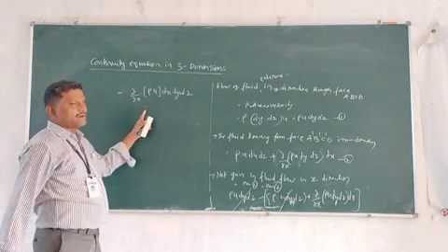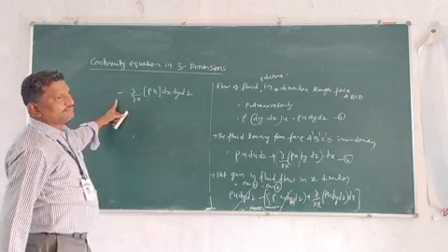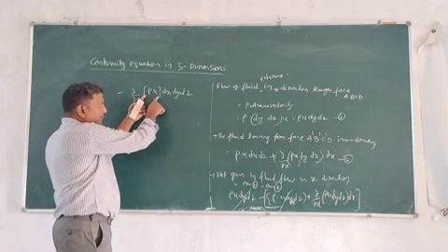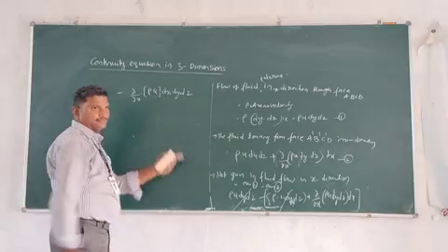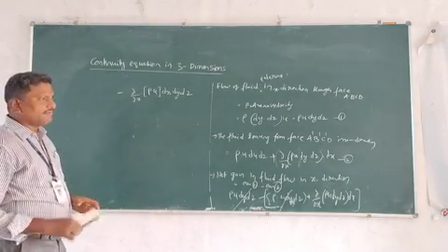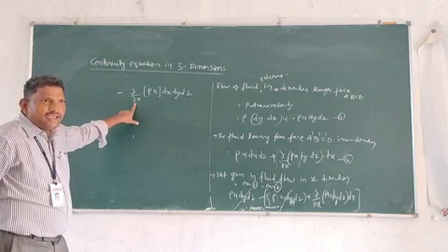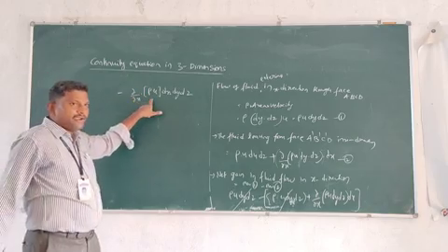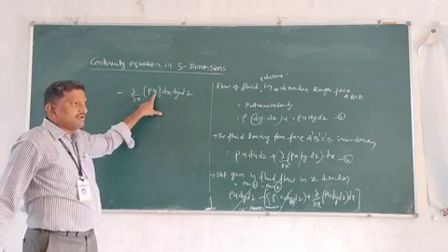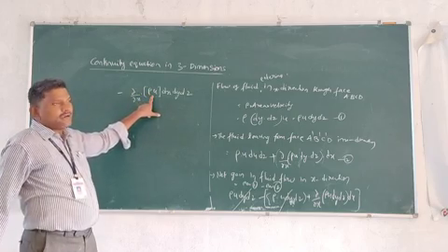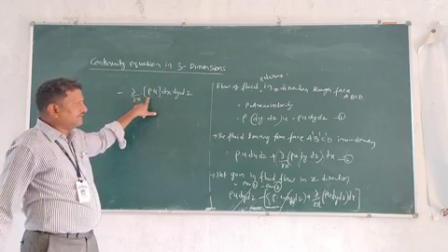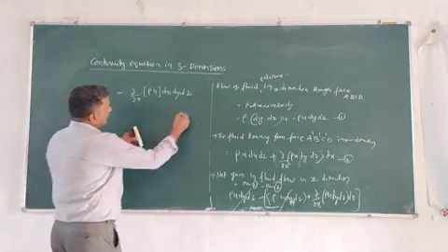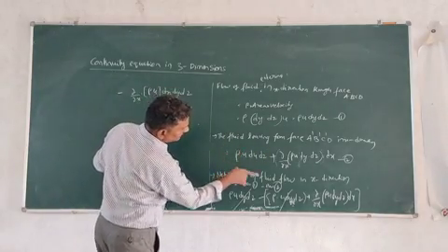So net gain in the fluid flow in x direction is minus dou by dou x of rho u into dx dy dz. What are the common phenomena we are seeing? Being x direction, we got dou by dou x. Being x direction, we got the velocity component u. Density is a constant, and this is a fluid element. Write it as equation 3.